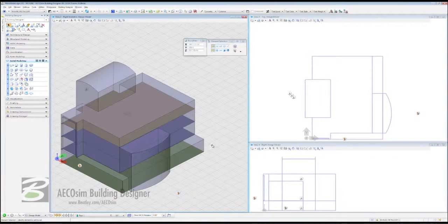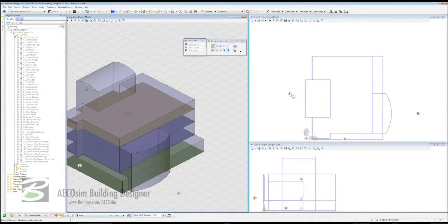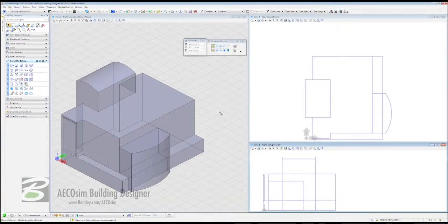Now to swap into that file to begin the construction modeling side of it, we'll just come past our task-based interface to Project Explorer. We're going to twirl down the project directories, the building sample and designs, and in there we're just going to double click on A underbar external walls DGN. Our conceptual model switches out for our construction design model now, and what we're going to do, the first thing is come back to our Solid Modeling tab, the last row, penultimate icon, Extract Faces and Edges, because we need to extract our atrium and a bit of our roof.